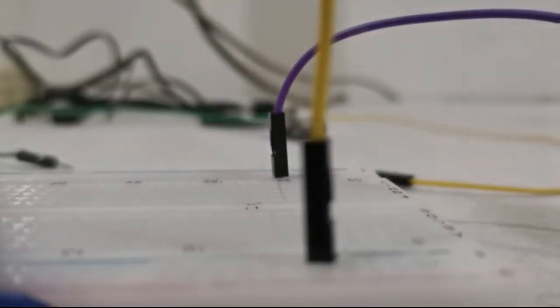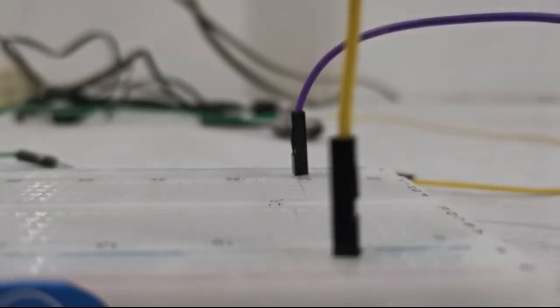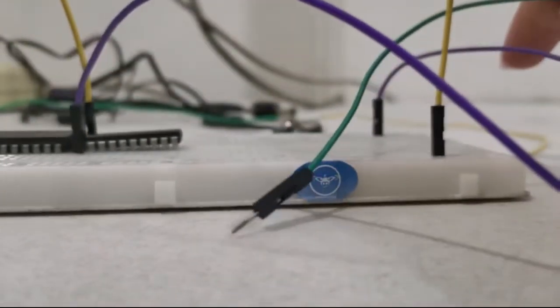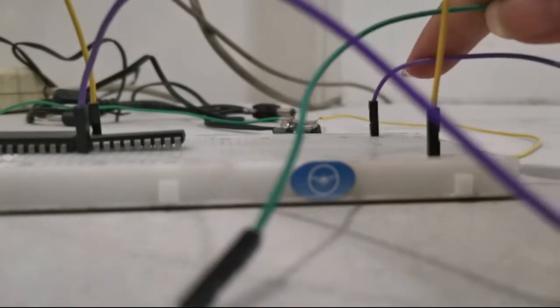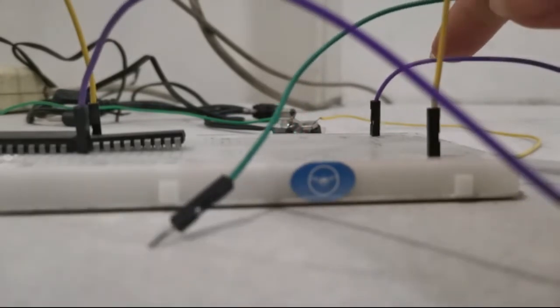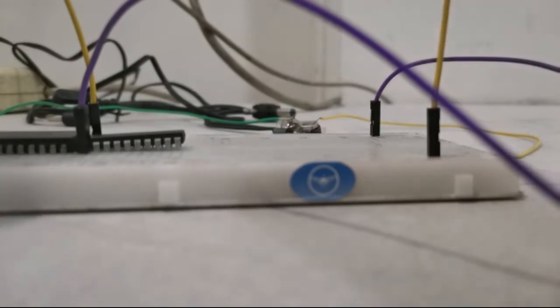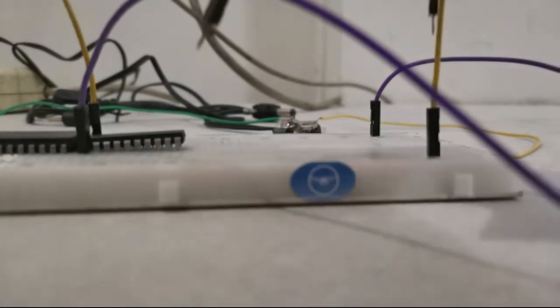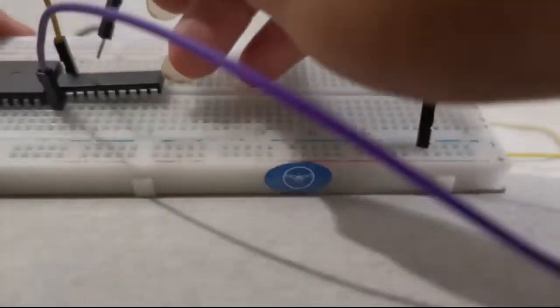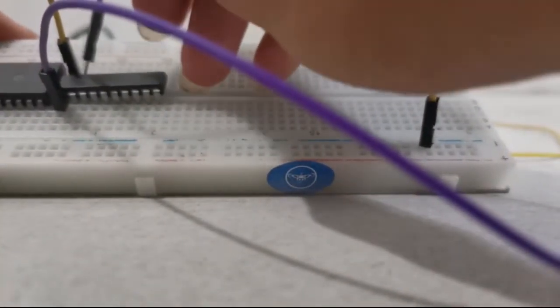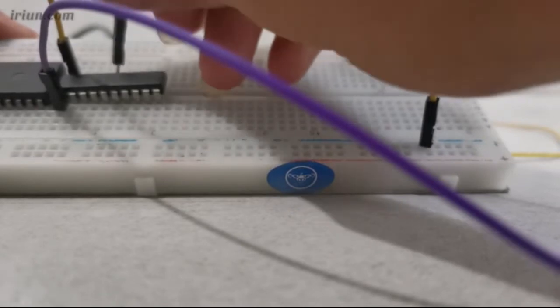And then after that, we'll be having our servo motor input, or what should we say this? This would be for the data signal controlling the servo motor. So for this, we'll be putting here at RC1, which is actually here: 1, 2, 3, 4. Skip here, and then we'll have it right here, port RC1.